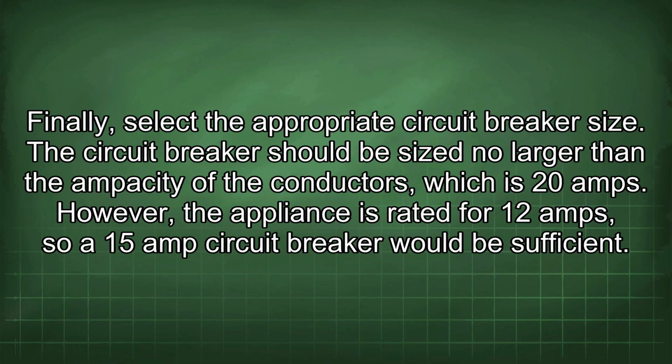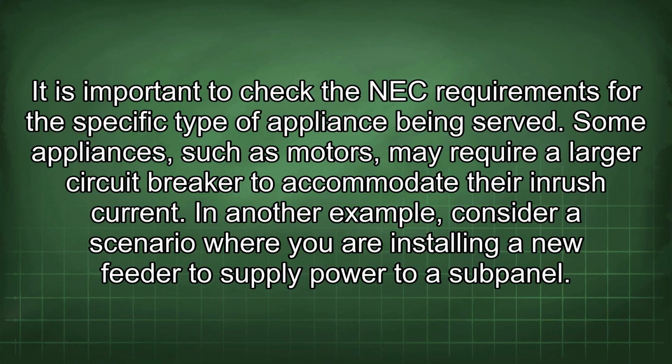Finally, select the appropriate circuit breaker size. The circuit breaker should be sized no larger than the ampacity of the conductors, which is 20 amps. However, the appliance is rated for 12 amps, so a 15-amp circuit breaker would be sufficient. It is important to check the NEC requirements for the specific type of appliance being served. Some appliances, such as motors, may require a larger circuit breaker to accommodate the inrush current.